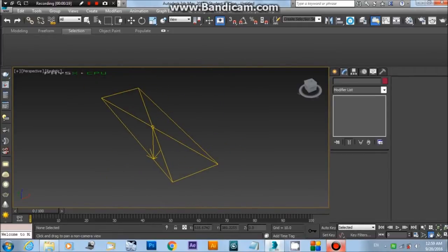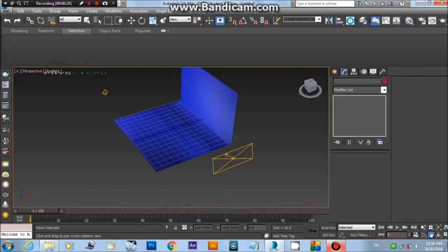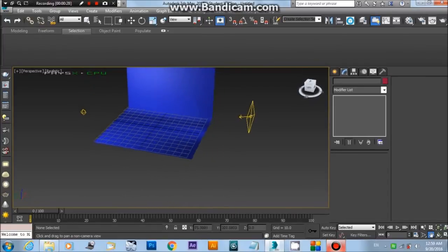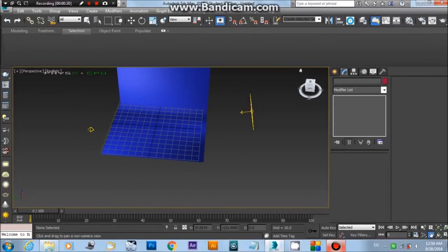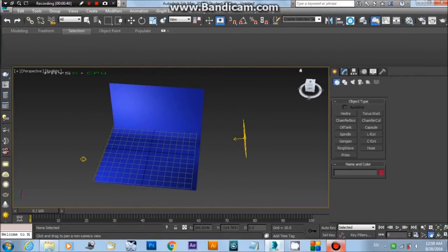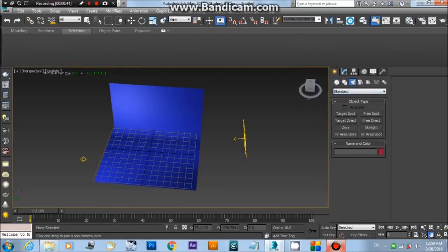One, the V-Ray light at the top, and now I will create the second one, as you see here, and the direction is here. Actually, that's very important. And please make the normal omni here. You can also find it from the standard lights, and the omni just here.